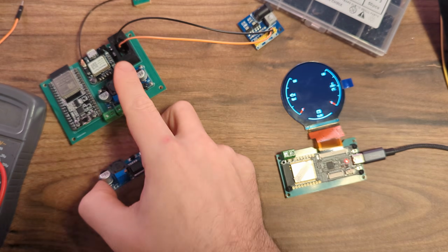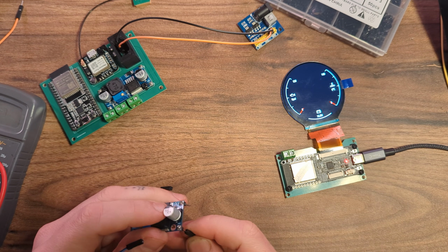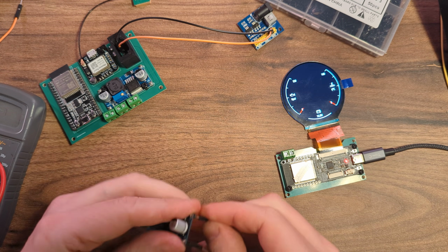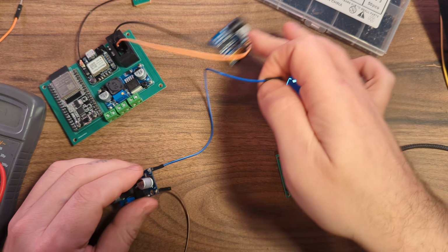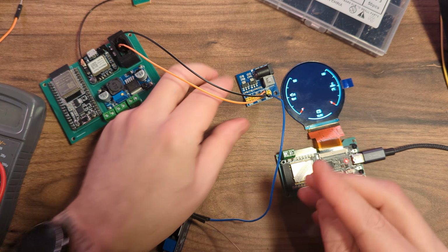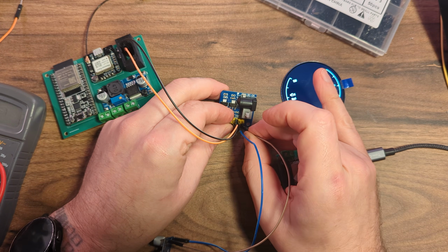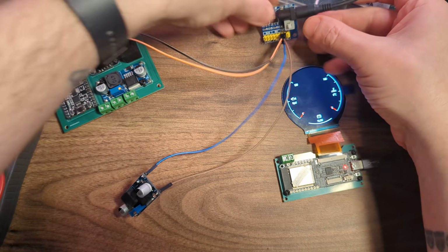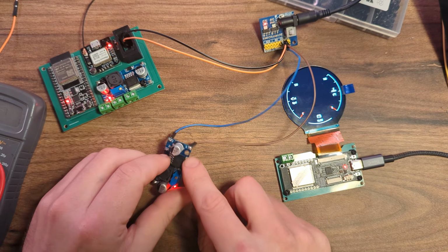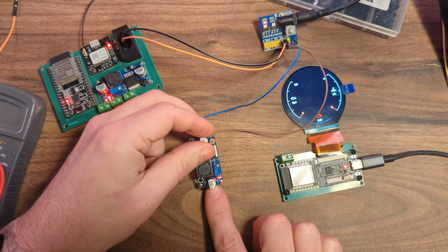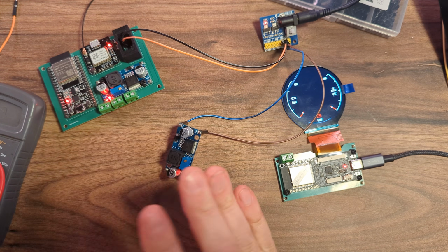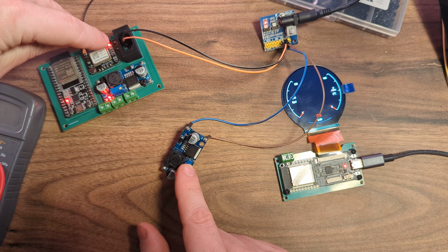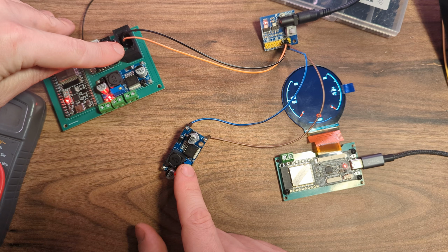And I've got another one of these identical step down modules, and I'm just going to put voltage in on there. Voltage ground on there. We'll connect it into this same distributor. Live on that side. So if I give that power, should all light up. And then I just want to measure this output voltage here and move it into a range that's actually safe for this. So remember we've got the step downs here, so this pin is going to want to receive a maximum of 5 volts.